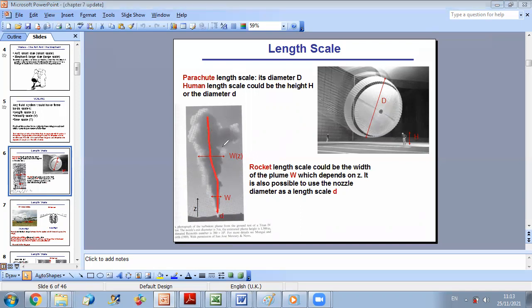You can simulate this by using, for example, smoke generation at a smaller scale, but still observe the same behavior. Okay, so what you should do is determine what the dimensionless numbers are that affect your result.